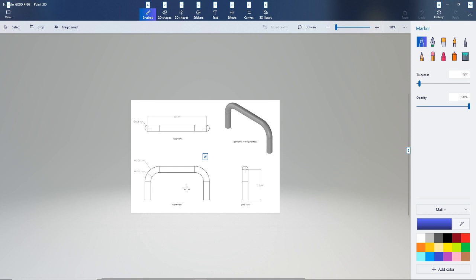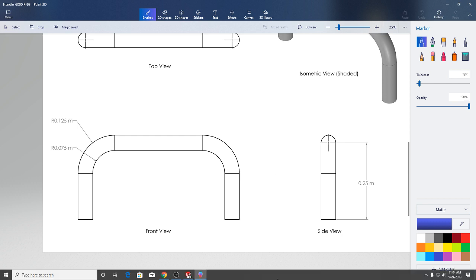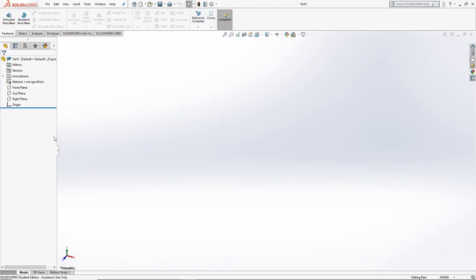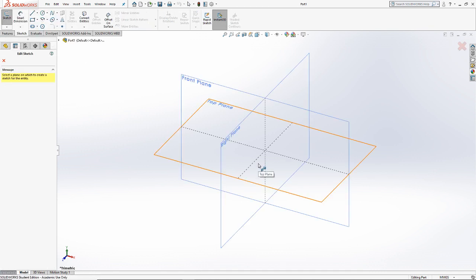The logic behind the swept extrusion is that if we draw a cross-section of the shape we want to extrude and then a path for it to follow, we can create 3D models that are like a linear extrusion, except the extrusion doesn't have to follow a specific line. So if we were to approach that in SolidWorks, we have to create 2 sketches, at least in theory. Those 2 sketches will make up the cross-section we want to extrude and the path along which to extrude. The cross-section has to start or end the path.